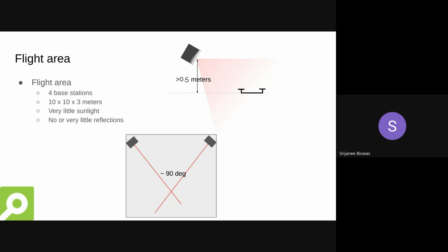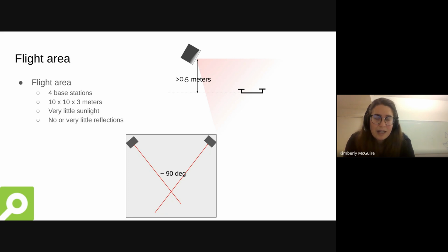I think the Vive ROS package uses that library underneath. We have looked at that at one point, but our implementation is very different. Our EKF measurement model is very different as well. The geometry estimation is also very important, because if one of the base stations is not estimated at the right position, then that will completely put the positioning off. When we compared back in the day, our positioning was better. But it's onboard the Crazyflie, so you still need to transfer it back to the computer in case you want to log it.